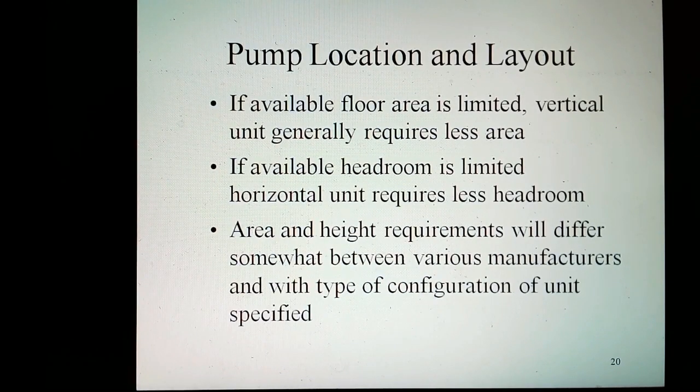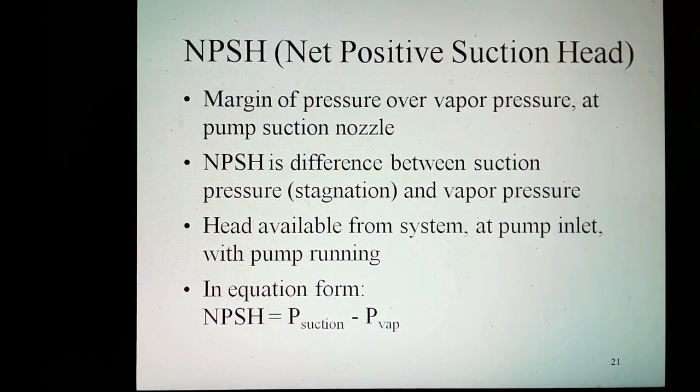Pump location and layout. If available floor area is limited, the vertical unit generally requires less area. However, if available headroom is limited, the horizontal unit almost invariably requires less headroom. It should be kept in mind that area and height requirements will differ somewhat between various manufacturers and with the type of configuration of the unit specified.